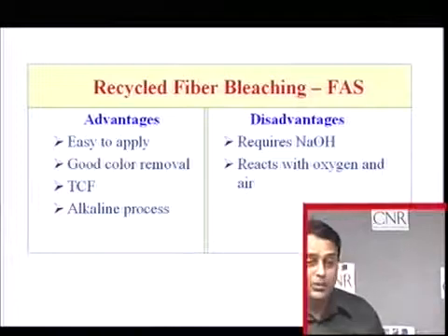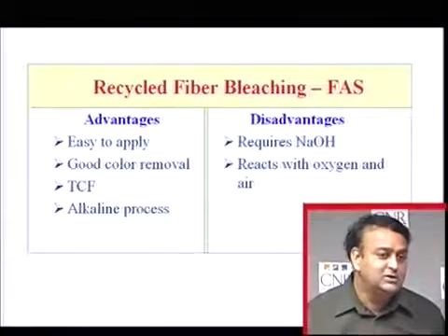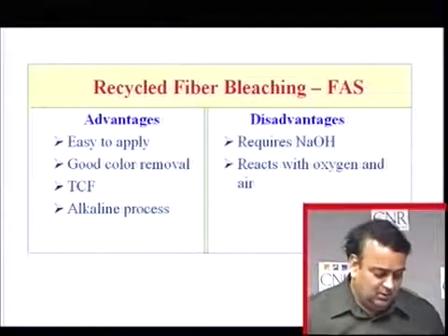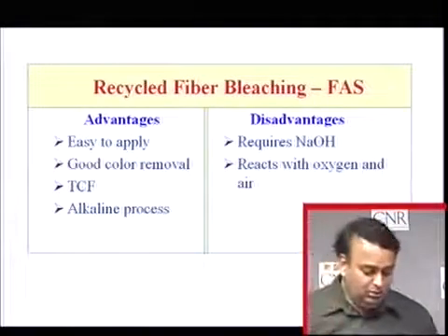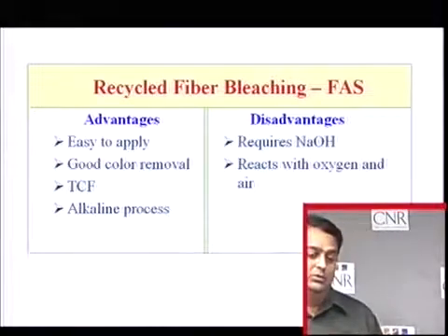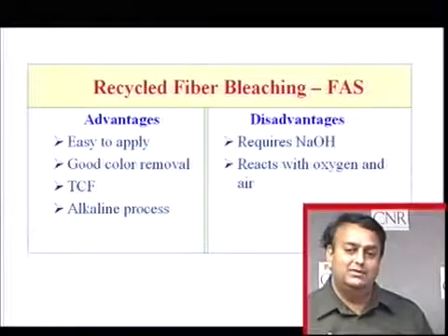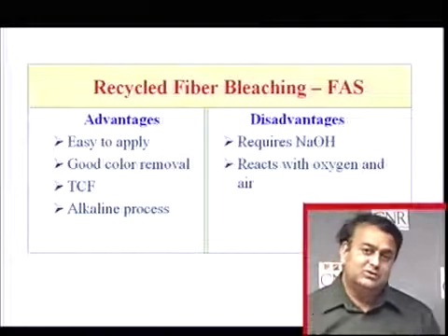Advantage, it is easy to apply. It is available in powder form. You dissolve it to form a liquid. Sometimes you dissolve it with caustic and then you pump it to the process. Excellent color removal, total chlorine free level, and it is an alkaline process. In the case of hydrosulfite, you may have to drop the pH sometimes to get the dyes out. But in the case of FAS, you need a pH of 9.